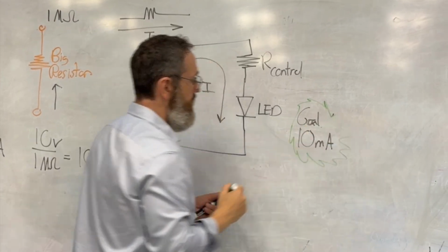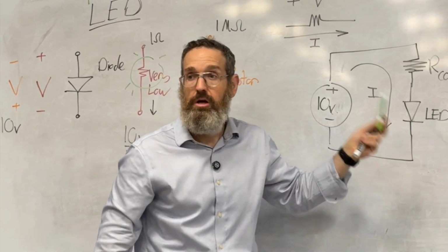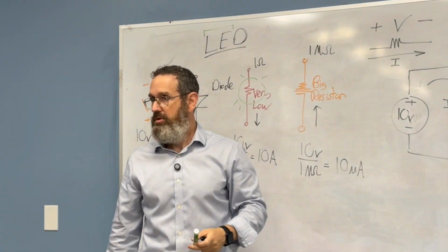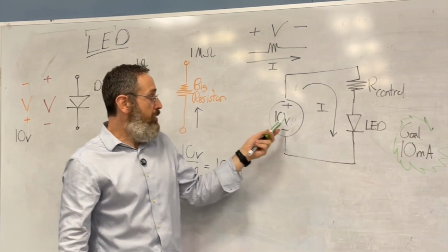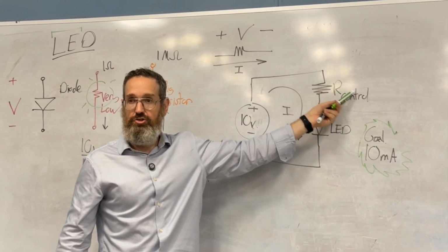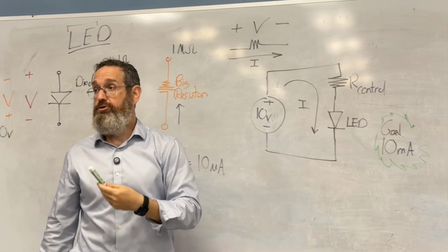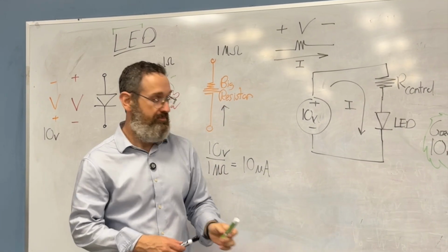It means glow, okay? If you get 10 milliamps through the LED, it's enough for it to glow, but it won't blow up. So it's a design problem. Now, this is 10 volts, this is given. This is the only parameter you can control in this design problem, right? So how do you pick it?